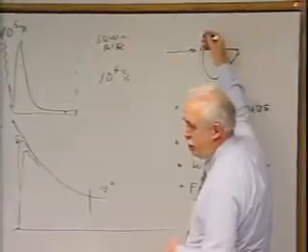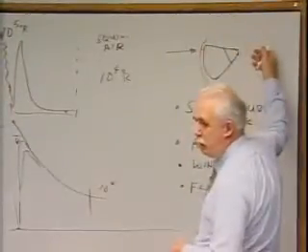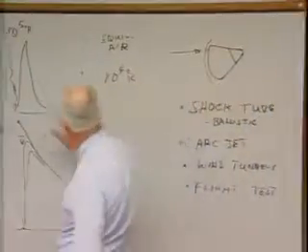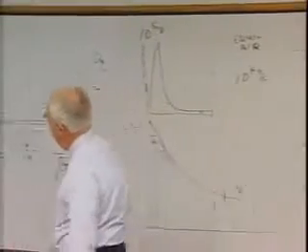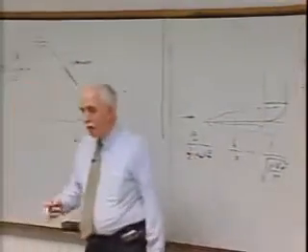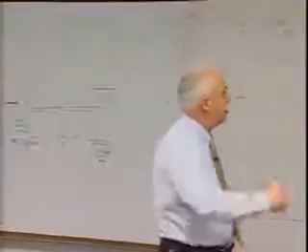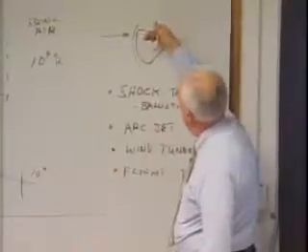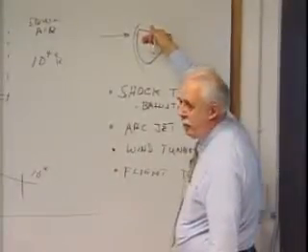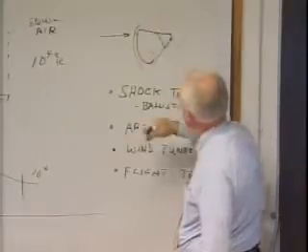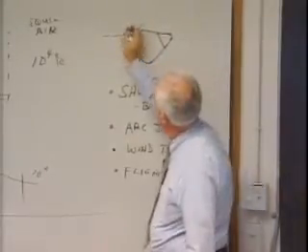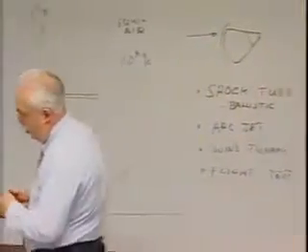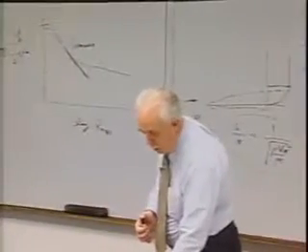At altitudes above that, the flow could be completely out of equilibrium. It hasn't gotten back to equilibrium because this characteristic time is directly proportional to pressure, which is directly proportional to free stream density. So at higher altitudes, it's out of equilibrium. And as you'll see shortly, Shuttle is at much higher altitudes than Apollo, and I'll explain why. At lower altitudes, this compresses, and it's predominantly an equilibrium radiation. And that we were able to characterize.